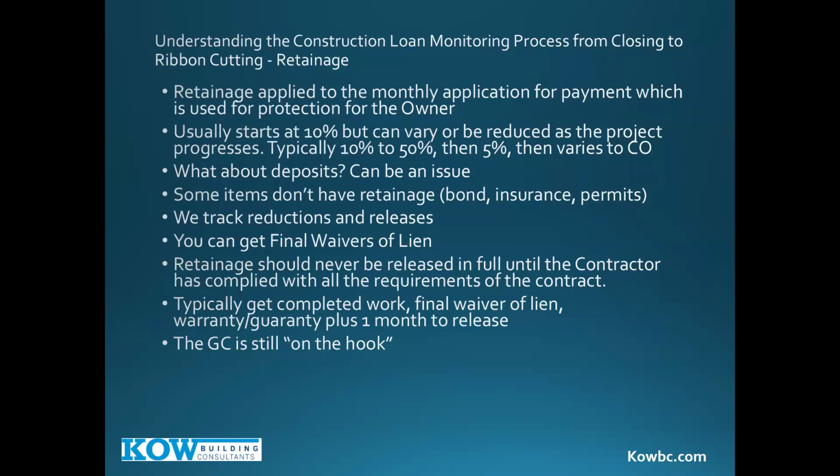So a good example would be we had a project where the framer was done and said, we'd like all of our retainage released, please. And the GC said, no, I'm going to hold it for a couple more months. And the framer was not happy. Well, as it turns out, the plumber came in, started doing all the wet walls in the bathrooms, and said, you have a problem. Your framer used an old set of plans, and on one of the apartment lines, one of the walls moved 6 inches due to the trash room on the other side, and the framing was done on the old plans. They had to come in and move that one wall in one apartment on each floor 6 inches. Not a huge deal, but certainly not a 0 deal.